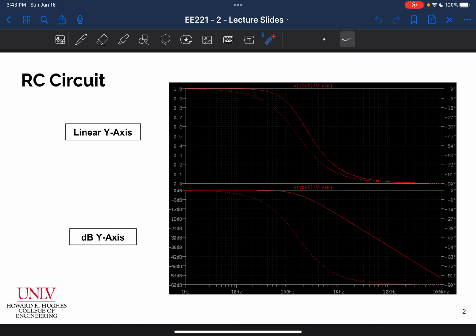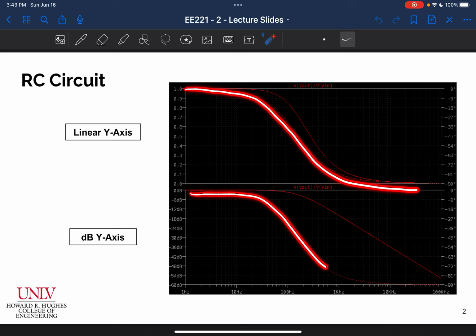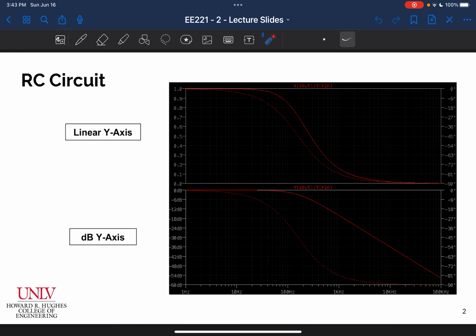The difference between these two plots, the exact same data, right? The phase is the exact same. I'm still going 0 to -90, 0 to -90. You can see that the phase plot looks identical in both cases, right? It's the exact same phase. The only difference is that the magnitude is no longer plotted on a linear axis. Okay, these dBs, or decibels, are a logarithmic unit.